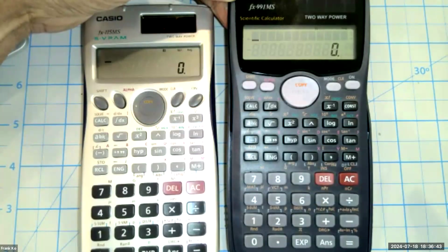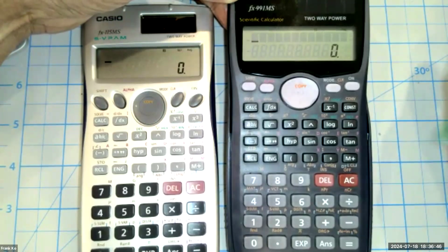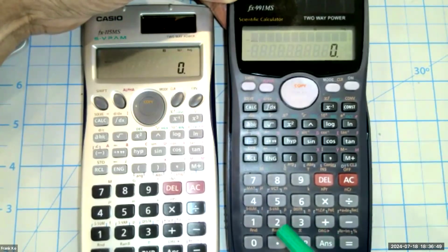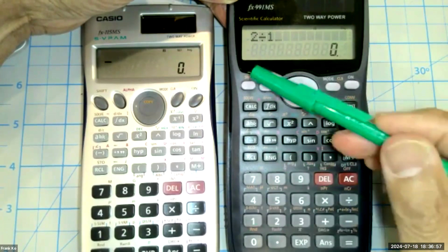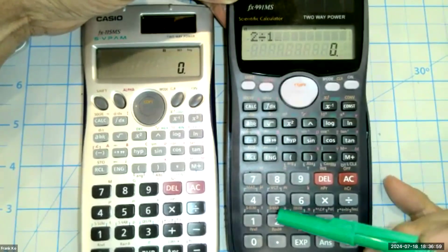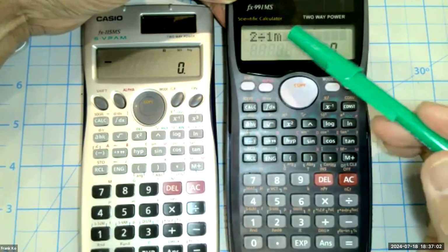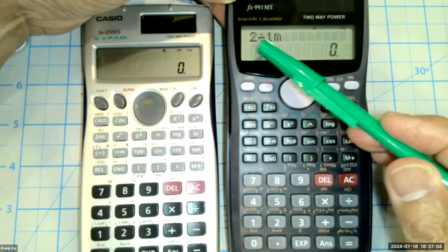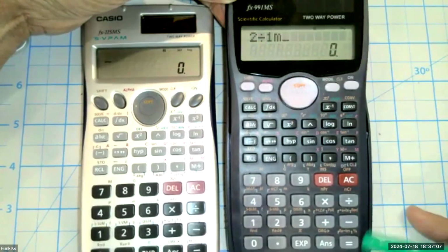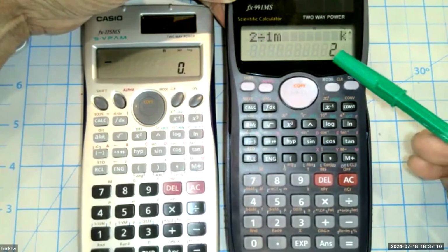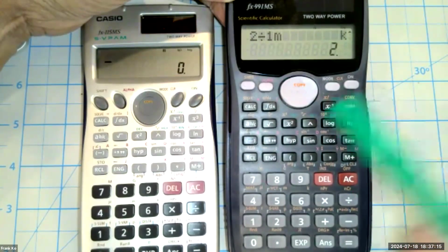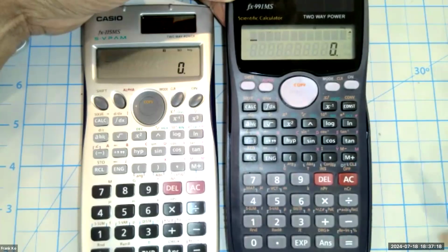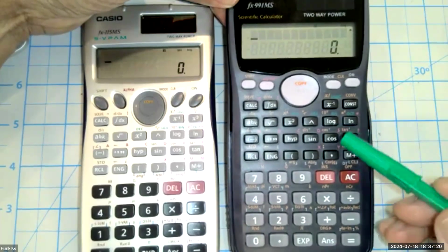So using our prefix calculator, what we're going to calculate is 2 volts divided by 1 milliamp. So that is clear. We're going to enter the 2 and divide by, and 1 milliamp is keyed in as 1 shift. The milli key is this one here, and you can see on the display I've got 2 volts divided by 1 milli. If I hit equals, I immediately get 2 kilo. Okay, 2 kilo. Now I can do the same calculation without the prefixes. If you don't happen to have a prefix calculator, it would be done this way.